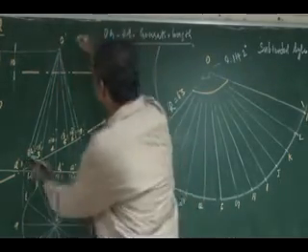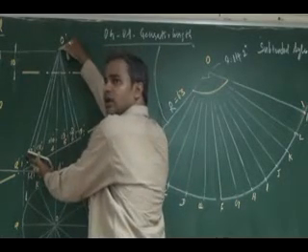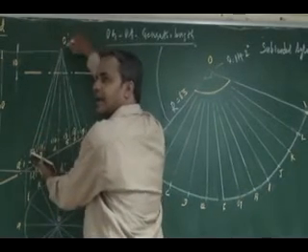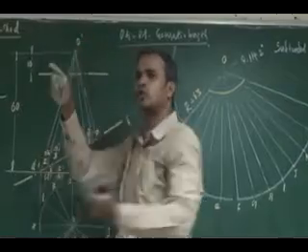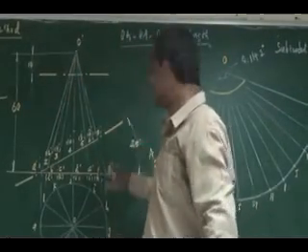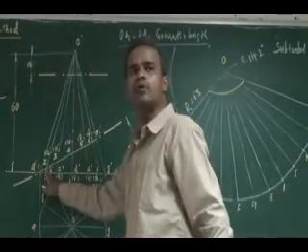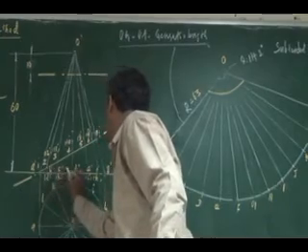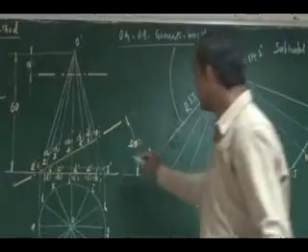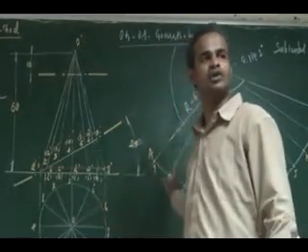These 2 and 12 cutting points, directly I cannot measure this length. This is not an actual generator. It doesn't give me the true generator length. So which one will give me the true generator length? OG and OA. So I have to project this 2 and 12 to OG. I have to measure the length for 2 and 12.